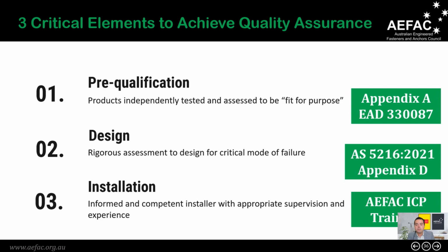Installation in accordance with the manufacturer's installation instruction is very, very important. For post-installed rebar connections, the required hole depth may be very large compared to chemical anchors, and hence the installation quality is extremely important. The installation must be carried out in accordance with the manufacturer's installation instruction.